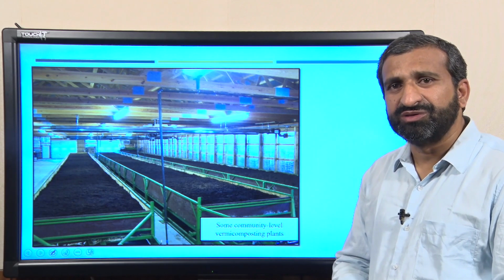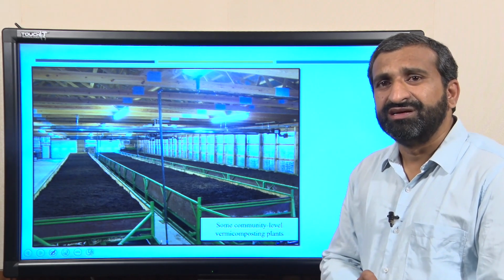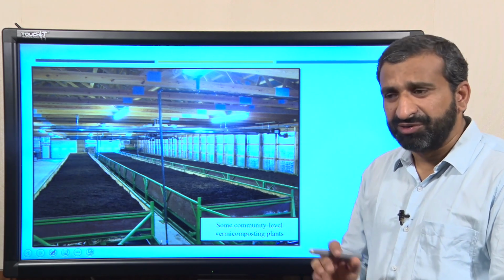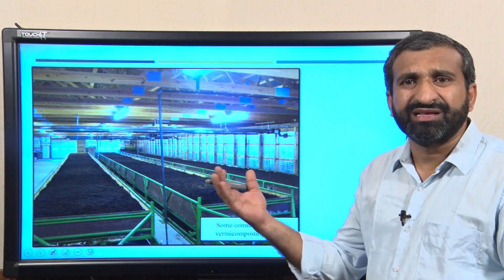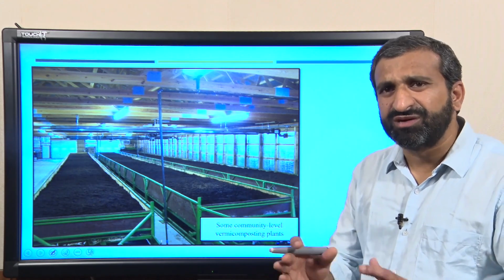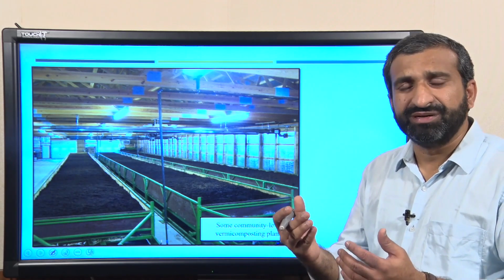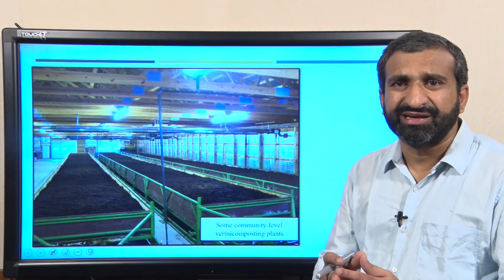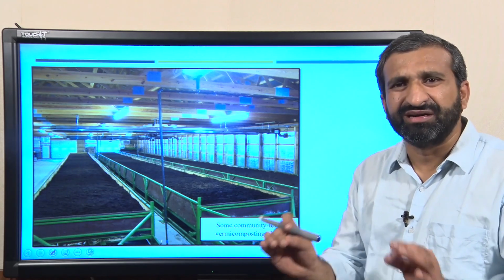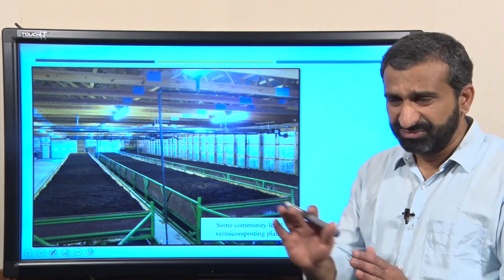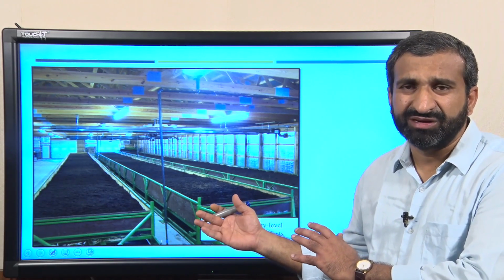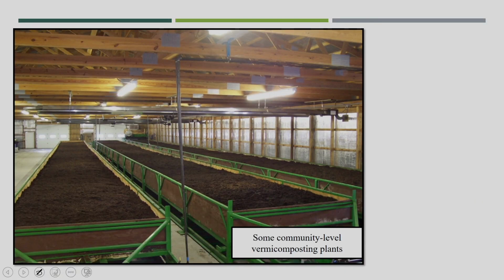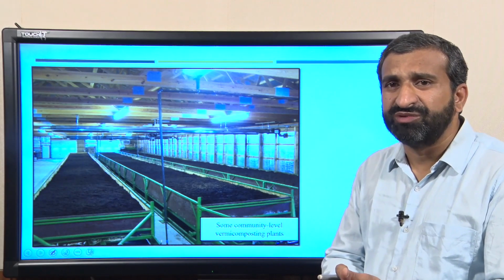And under the Swachh Bharat Mission also, a lot of discussion has been given to the decentralized treatment process, especially for biological waste, because dry waste can easily be collected by compaction trucks and can easily go to the recycling facility. Further segregation is somewhat difficult at household level. Maybe at source metal and glass can be easily segregated, but for paper, plastic, rubber, leather, further segregation is not possible at household level, apartment level or community level. It could go to the centralized facility, especially the dry waste, but the biological waste creates a lot of problems not only on the disposal side, but its collection is also a very difficult process,